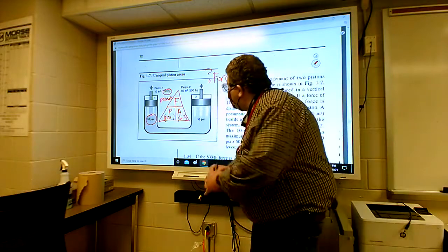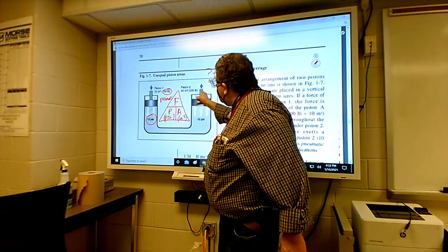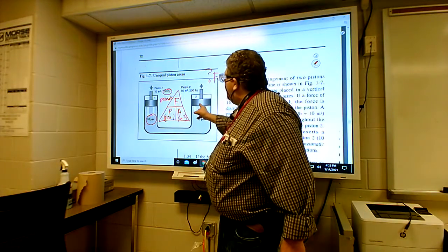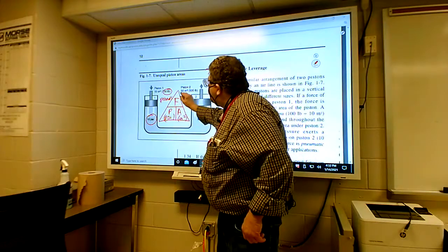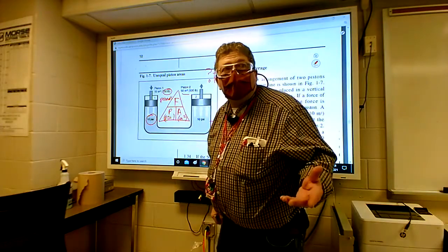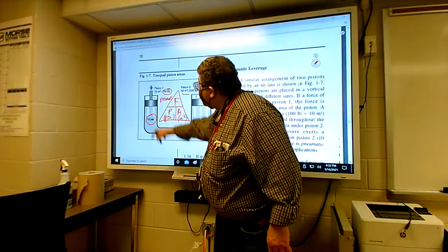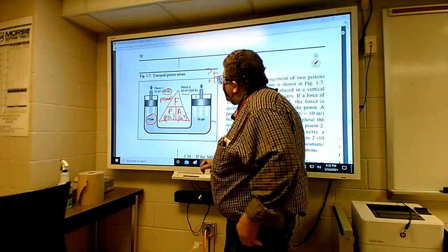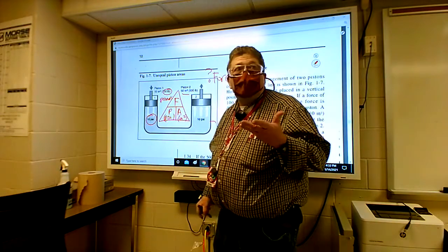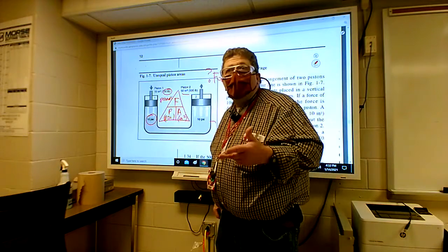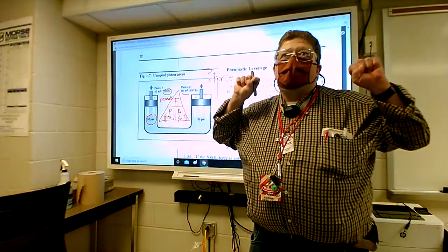Yes, exactly. Look, if you take here, we're gonna cover up F. That's the output force of this, which is the unknown. And we know the size of the piston went up to what? To 50 square inches. It went up times 5. So it's 5 times bigger than this one. And so we know the area, and then we know the internal pressure pushing the piston. So you can calculate the output force, or you can calculate how much weight the cylinder can lift.